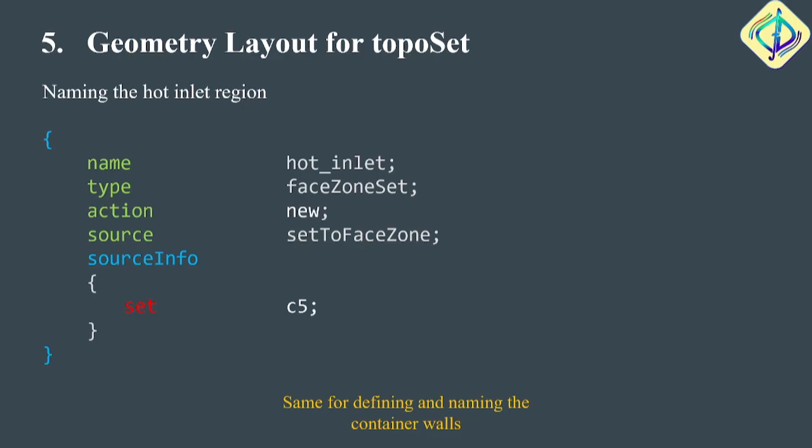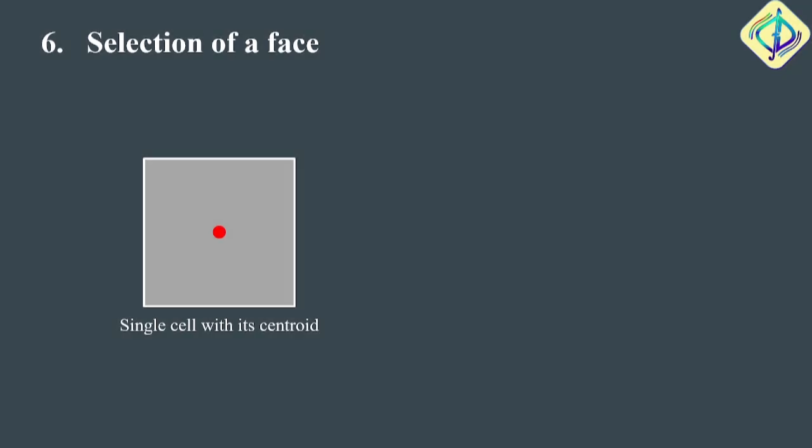You'll have your front, back, top, bottom, left, right, and then you will also delete all the patches, or all the areas where the pipes are located, for the faces. At your front and back you will have that particular region where the pipes are, so you can delete it out. Also, when you're dealing with the hot inlet and hot outlet, you can delete that particular area out of the face.